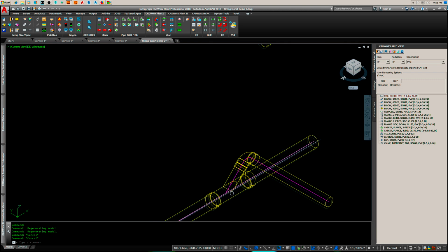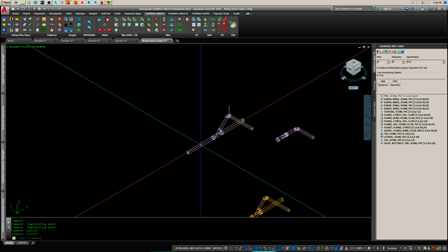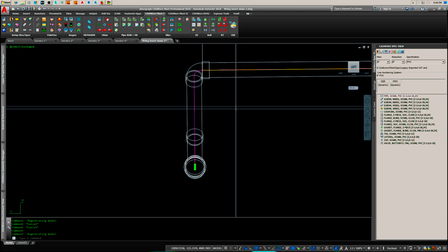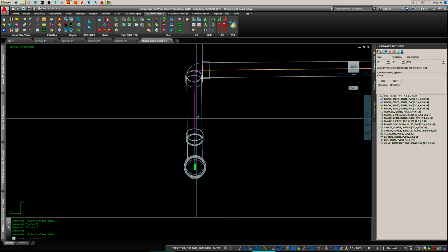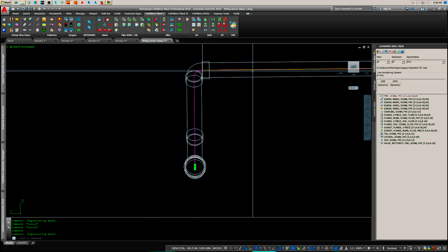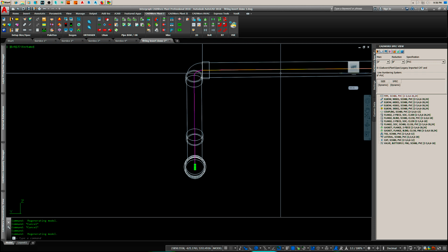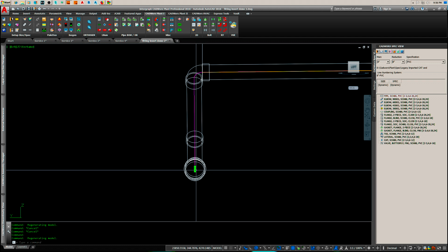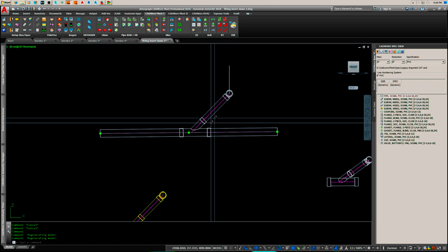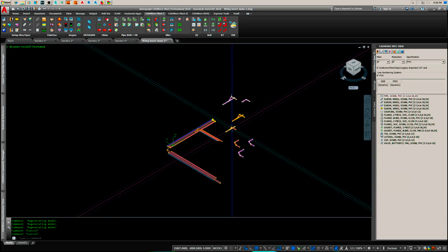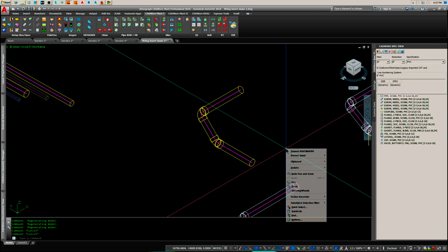The proper way to do it is up here. You rotate the Y, you rotate this whole assembly 0.5729 degrees that way, which gives you your 1% slope here. But before you do that, you want to rotate down the longitudinal axis of the main first, and then rotate the main to its slope. And I'll give you a quick demonstration of how this works.